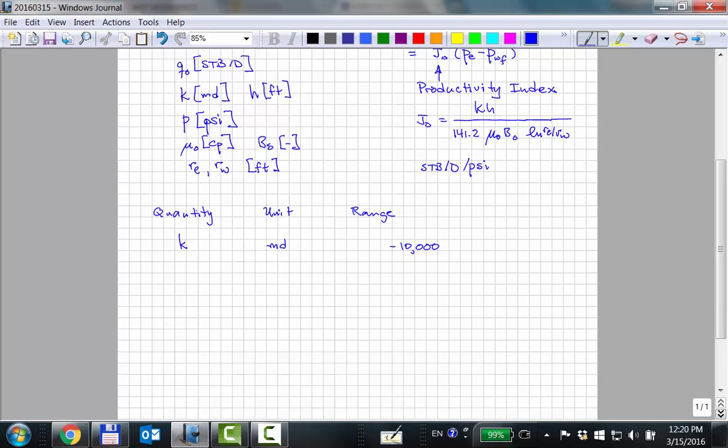Now, prior to the shale boom in the United States in the last 10 years, the lower range of permeability where we could produce economic amounts of oil and gas, with a single vertical fracture, which is what we would have been using in the 70s and 80s, was probably 0.001 for gas and for oil probably 0.01.